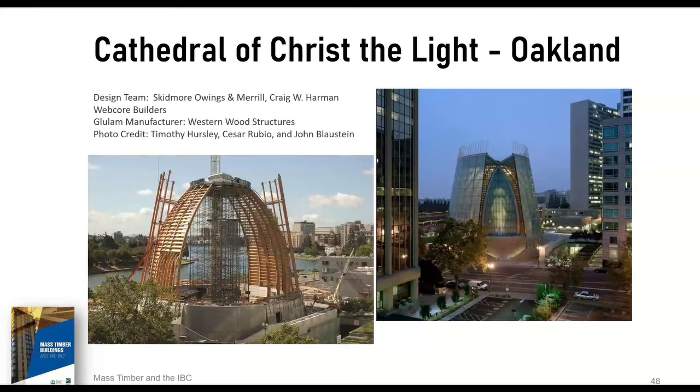However, the use of timber proved to be a pivotal economic advantage that actually won Skidmore, Owings & Merrill the design contract. The 21,000 square foot structure cost $80 million to build. The strength of the structure is achieved through glulam and pretension steel rod space frames. To give you an idea of the scale, the glulam ribs are 10 3/4 inches wide and 19.5 to 30 inches deep. The louvers that contribute to the dynamic light filtering experience are 5 1/8 inches wide and 22.5 to 39 inches deep.